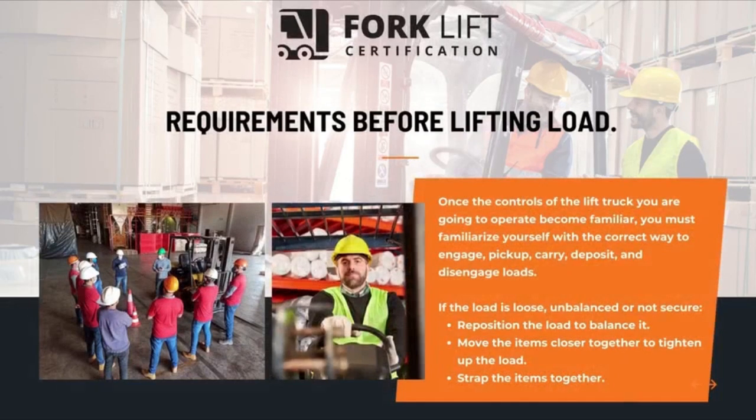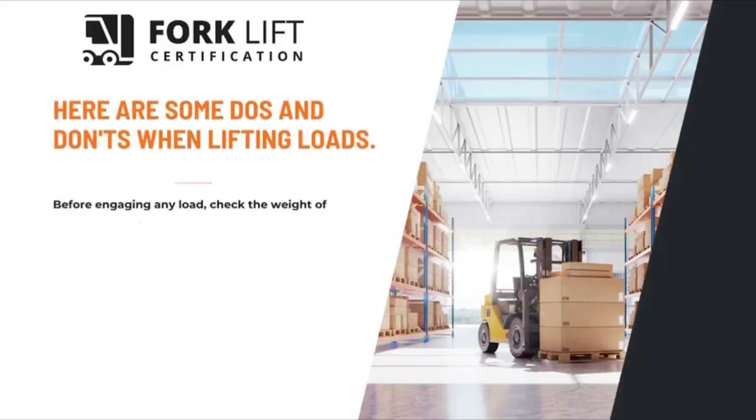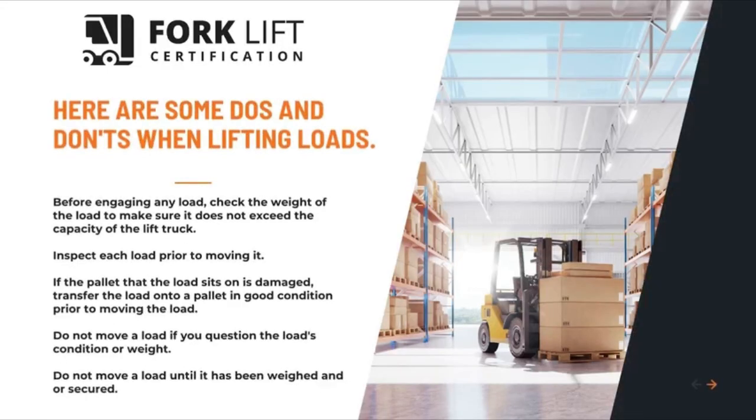Requirements before lifting load. Once the controls of the lift truck you are going to operate become familiar, you must familiarize yourself with the correct way to engage, pick up, carry, deposit, and disengage loads. If the load is loose, unbalanced, or not secure, reposition the load to balance it. Move the items closer together to tighten up the load. Strap the items together. Here are some do's and don'ts when lifting loads.